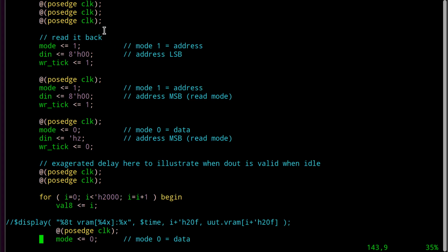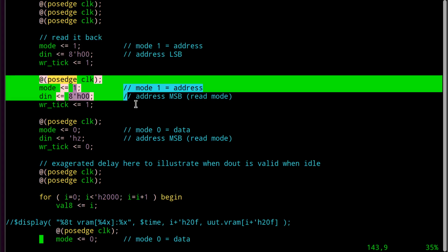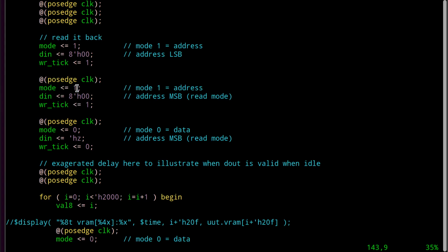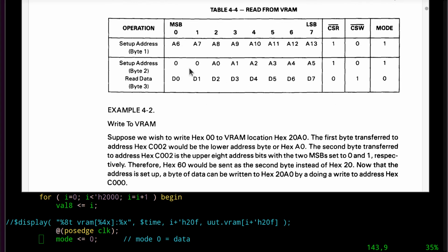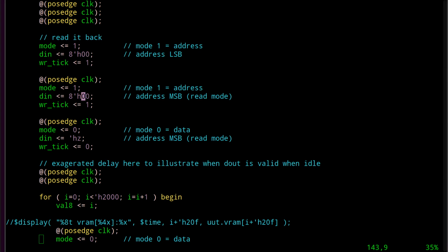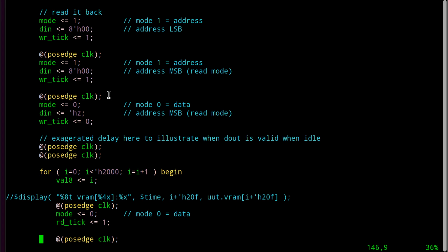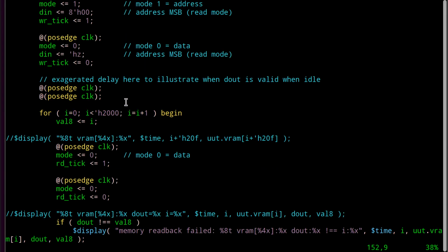And then what are we doing here? We're going to go in and set an address for reading. And remember that this value for the read setup is all zeros. There's the write, and the read has these zeros up there. So that'll just be 000. For both halves. These are slammed back to back rather than having the pause in between like we saw above. So this will test, will my state machine work in the ludicrously fast mode, which will never happen in realsies, but it should, all right, to make sure that that's okay. Then we have a pause, and then we have an exaggerated delay.